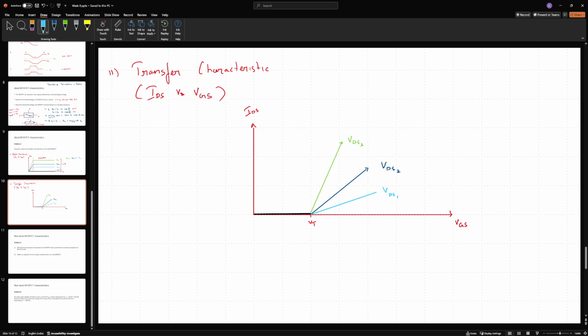Now again, one can ask the question. See, the cutoff region is very well characterized. In the off region, no conduction takes place. So I can define the off region over here, and it is on in this side. Now this gives me various rates of increase. And from here it's rather intuitive to see that the more charge that is available, the higher the current. So increasing VGS will increase the charge that is available and therefore the current is increasing. Now even with a lesser charge, I can have more current if the driving voltage is larger. Therefore from that I can directly say the following.